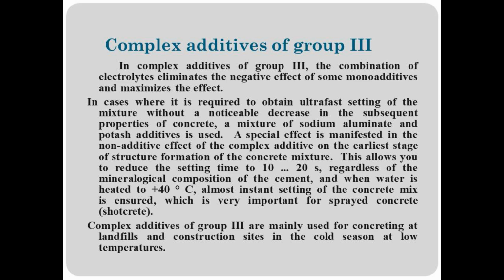In cases where it is required to obtain ultra-fast setting of the mixture without a noticeable decrease in the subsequent properties of concrete, a mixture of sodium aluminate and potash additives is used. A special effect is manifested in the non-additive effect of the complex additive on the earliest stage of structure formation of the concrete mixture.